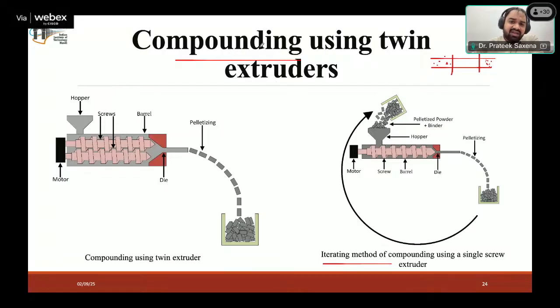Now imagine I'm making a cube, and at some place there is a lot of metal powder, while in another place there is only plastic, with no metal powder at all. Now when I'm going to do the debinding and sintering, wherever there is only plastic, it is going to distort my structure completely, because there was no metal powder there. What would have sintered? The plastic which was present there has eventually gone away.